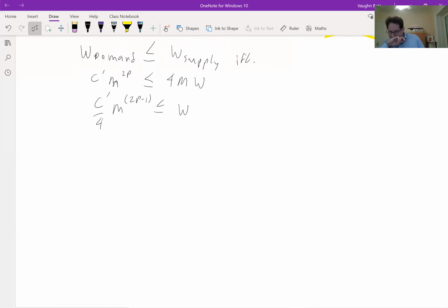So what does this tell us? Well, it's easiest to see if we put in some examples for this Rent exponent P. If P is less than or equal to 0.5, we saw last week, those correspond to circuits that have good locality. If we had a linear chain of processing elements, the Rent exponent was 0. Some FIR filters can actually achieve that, or again, a linear pipeline. If we have a two-dimensional structure, some kind of mesh or some kind of block of RAM, that has a Rent exponent of 0.5.